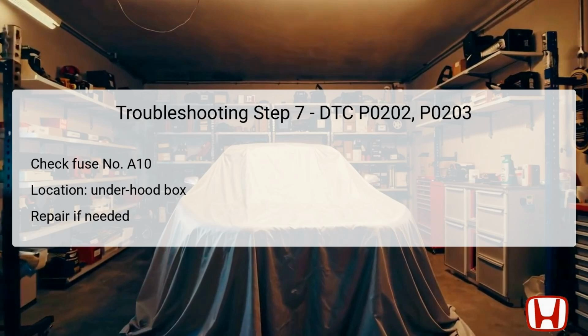As always, you will want to visually inspect the fuse and use a multimeter to ensure it has not blown. If the fuse is functional, it suggests there's an open in the +B INJ wire needing repairs. However, if the fuse is indeed blown, you have encountered a short circuit that must also be addressed. Replacing the blown fuse and repairing the short between the fuse and the injector relay is critical to restoring proper